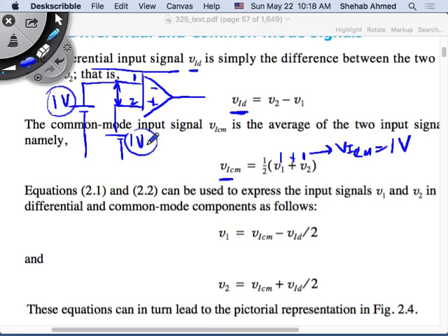So then of course I can draw an equivalent circuit like we did before, where I have a relationship between the input voltages and my common mode voltage. So I can solve for V1, for example, and utilize it here. If I solve for V1 and put it here, then at each terminal I have some common mode and some differential signal.